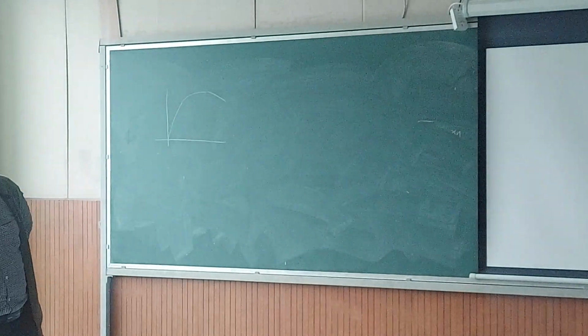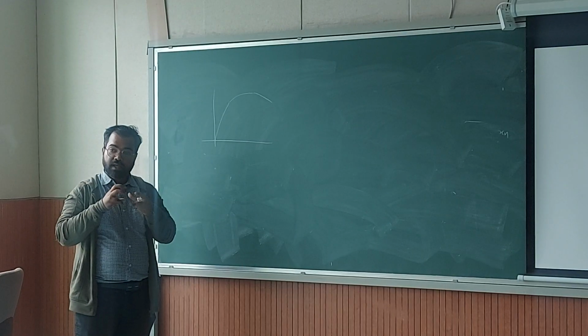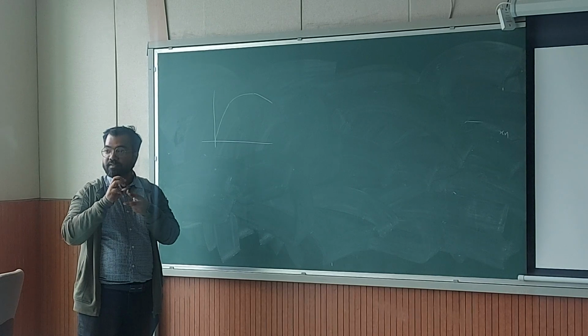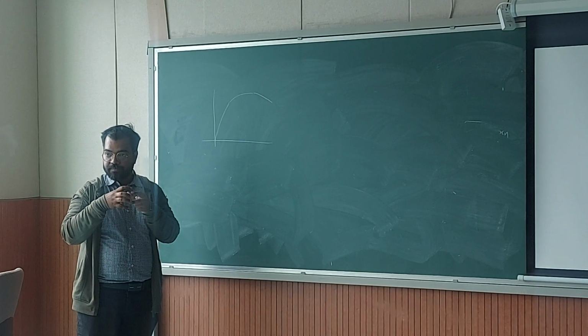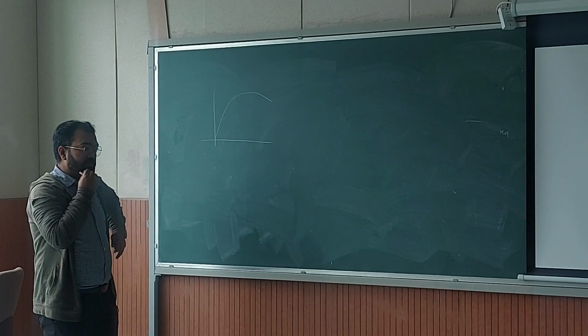So grain boundary sliding happens in creep. Okay, and if you have carbides which are sitting at the grain boundary, then they will not allow this movement. So they pin the grain boundary. Okay, so you need these kind of things.